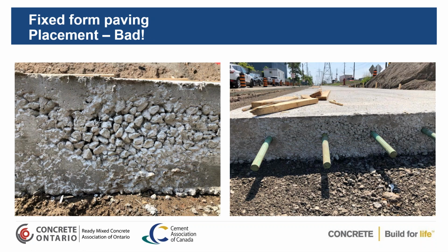However, in this case, we have a couple of issues. Here, this could have been an issue with, again, the forms not having the form release agent placed on them, and it took away some of the paste and fine aggregates. Or it could have been they touched the side of the form and ended up getting some honeycombing, some segregation in this area.